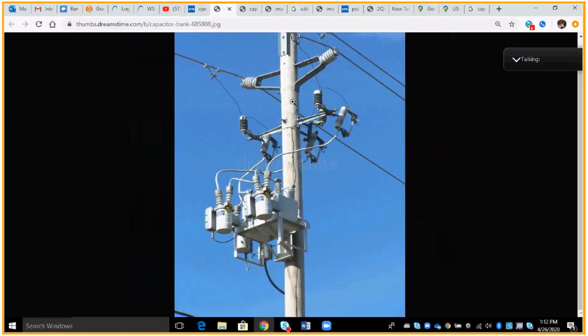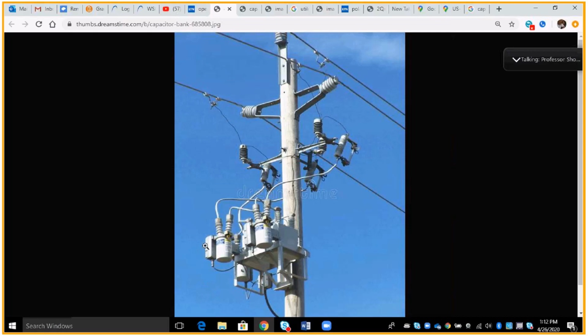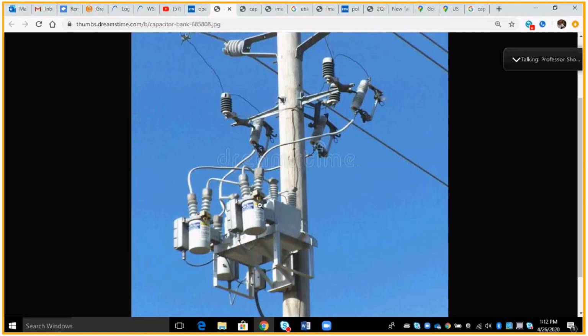And go back to this one right here. So we've looked at this part, different type of vacuum switch, but it's still got the yellow handle that you bring down. Down is open, up is closed. If you notice, these are down. It's supposed to be up in this little collar area right here. So these vacuum switches are open.